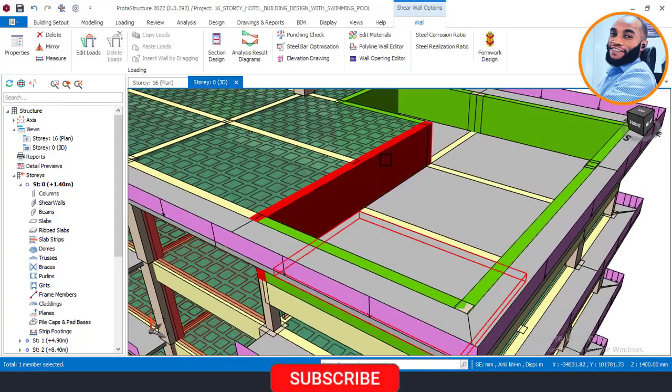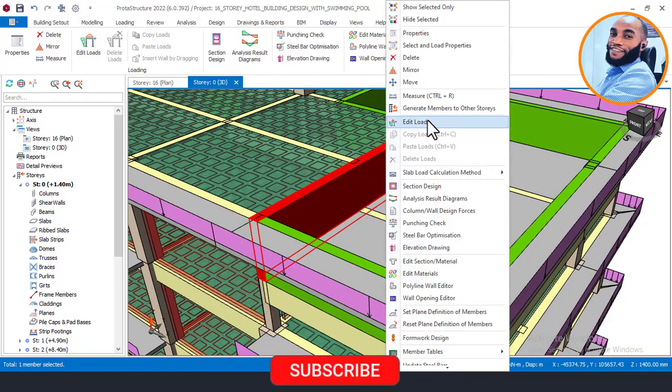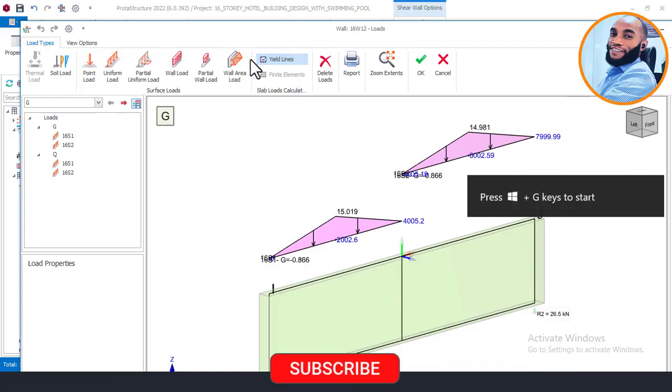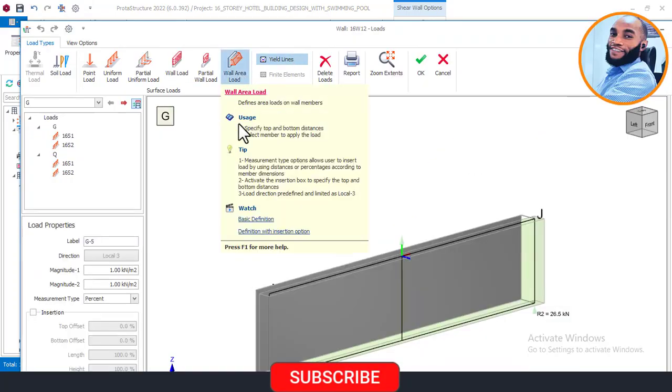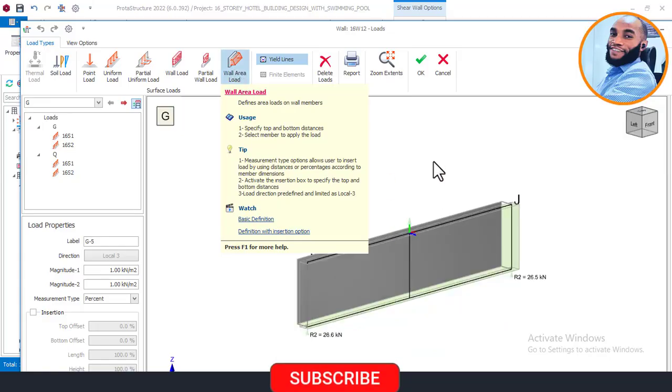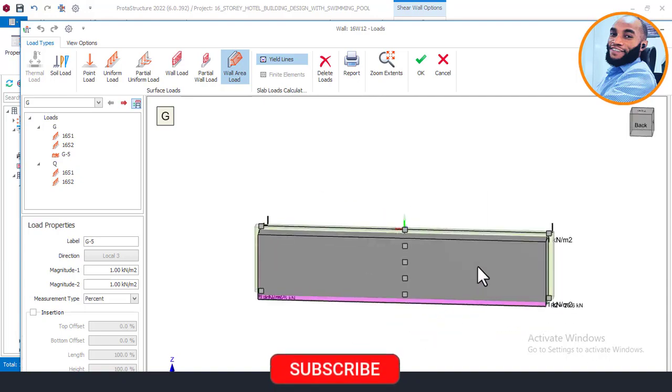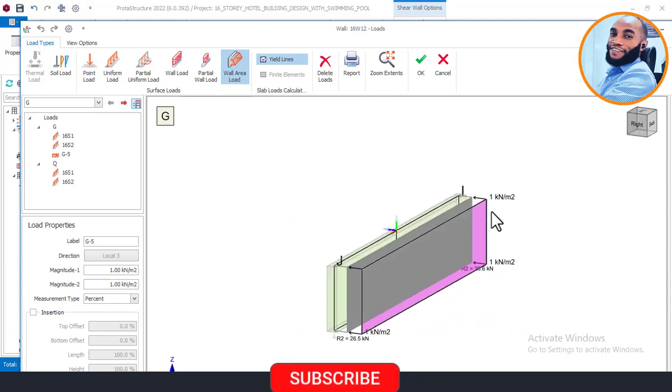So right now, I'll have to click on the wall, right click here, and then come here and say edit loads. Now on this edit loads, I will have to come here and click on my wall area load. Once I click on the wall area load icon, I'll have to come here and click on this icon of my wall, and I'll try to rotate this right now. You can see that your walls are already displayed, having a load of 1.0 kN per meter square.